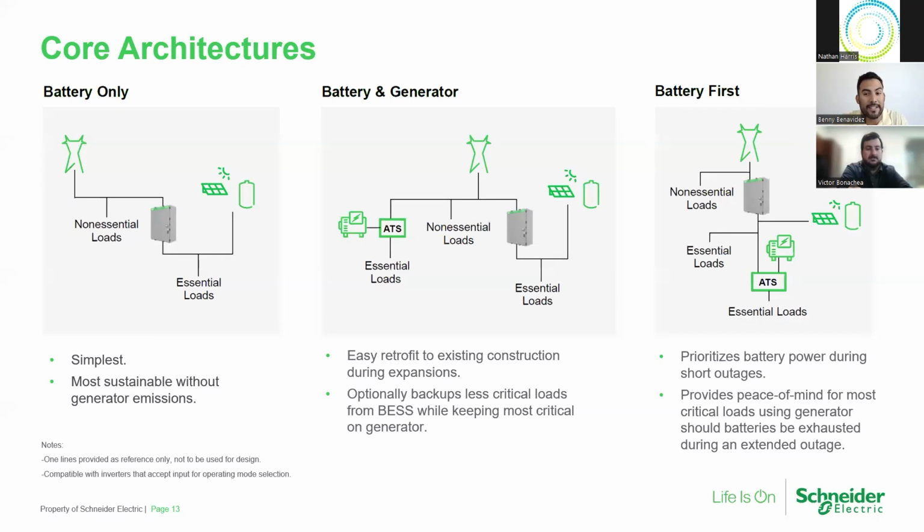What I mean by that is generators are legally required for life safety and legally required loads. So an ATS is there to provide power during those extended outages, think fire pumps, elevators, places like that. And then also you have SourcePack or an energy storage system providing power to other essential loads in your facility.